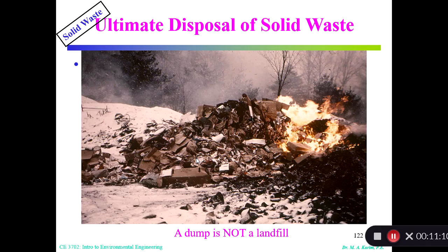So this shows a dump. The dump is not a landfill. This is a dumping site, meaning people are dumping waste here and there. It doesn't have any control: groundwater monitoring, groundwater collection, leachate collection, gas recovery, gas collection, or gas monitoring, and everything. No liner at the bottom and everything. But a landfill will have all of those. When we do the landfill design in solid waste engineering, you will understand that better.